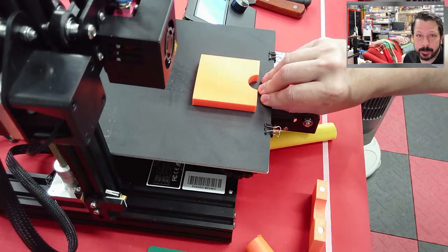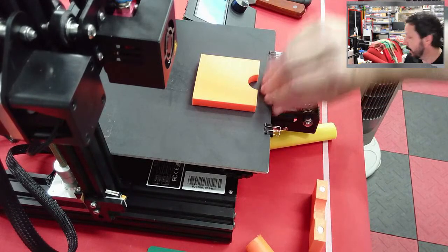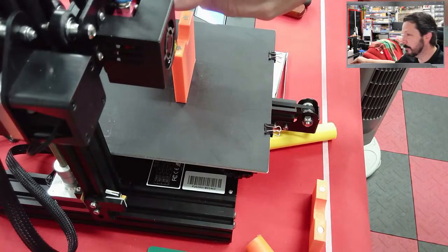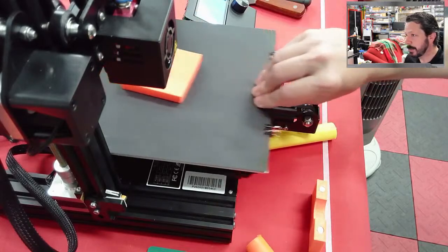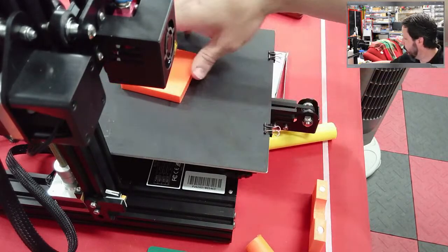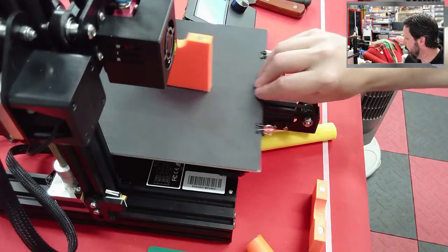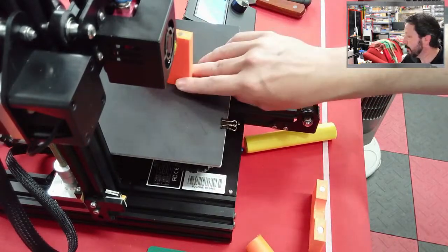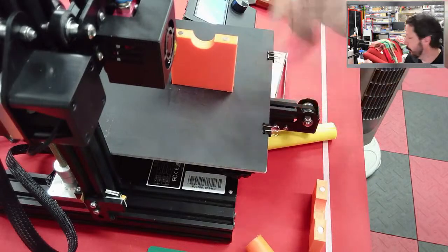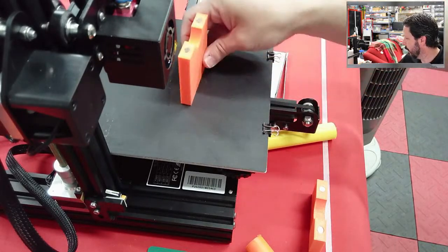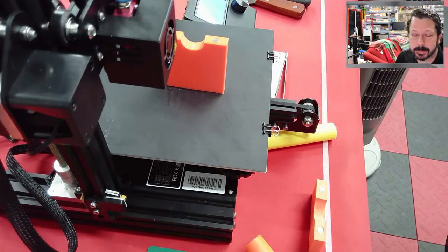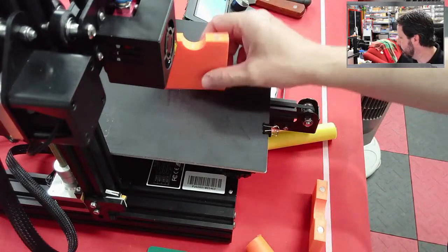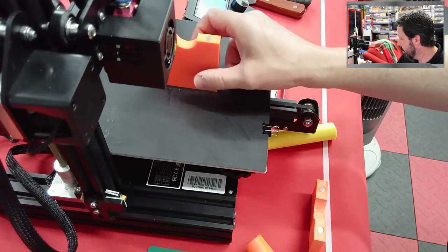And if it doesn't fall completely over, it's at least going to vibrate near the top. The taller this thing gets, the more it's going to shake back and forth as it moves on the bed. And if you print it this way on that same bed, it's sliding because it's not stuck, but it's not going to vibrate at the top nearly as much. So you might think about the shape of the part and the motion of the printer, how it's going to move around, and you can get better prints by printing things in different orientations.